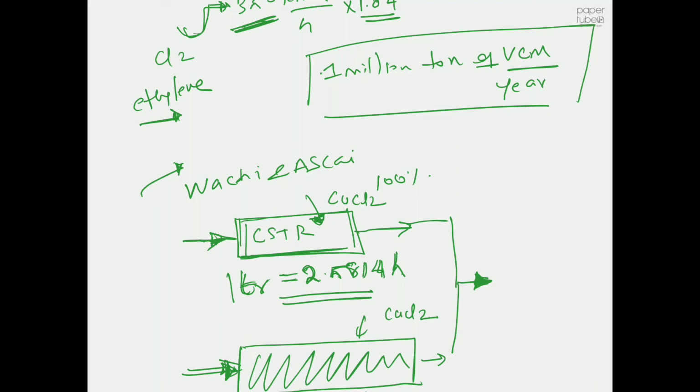Write the stoichiometry, the heat of reaction, the rate of the reaction, and the kinetic constants involved, and then draw this simple flow sheet which we did at the moment. Also take note of the temperature and the pressure, and remember key factors like low temperature chlorination.